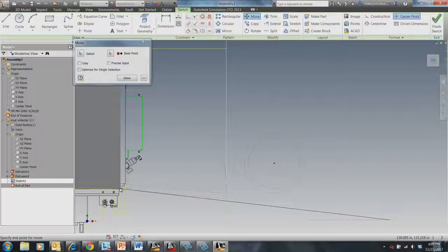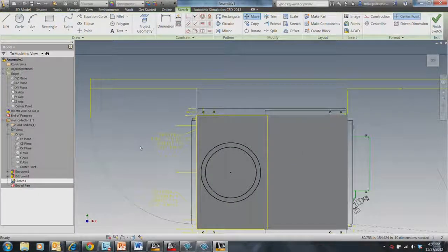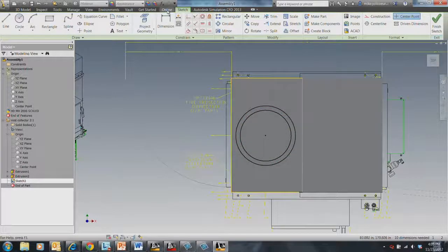Now, remember before we were talking about, is this going to be a changeable or a not changeable? Okay? So this is kind of an important thing to think about here for a minute. If this was going to be a non-changeable asset, if it was going to be something that wasn't going to change in size, I don't give a hill of beans about where that thing's located in the middle of there. I just go ahead and extrude it, go on my merry way, right? But in this case, what I'm looking at is this is something that I may want to reuse again. I may want to make it a different size. I may want to be able to resize it and rescale it. So what I wish to do then is to start constraining it a little bit. And constraining means we're just going to add a little bit of smarts to it.